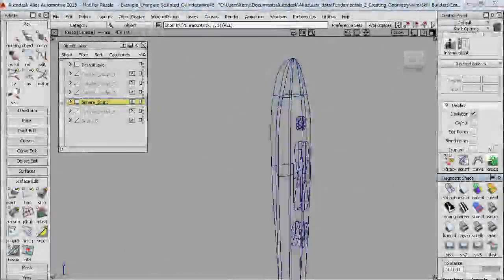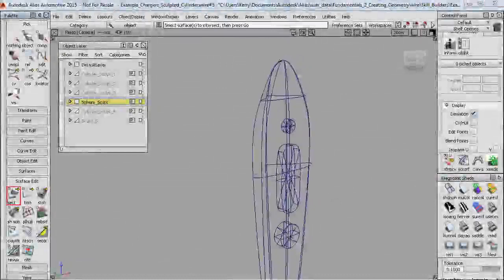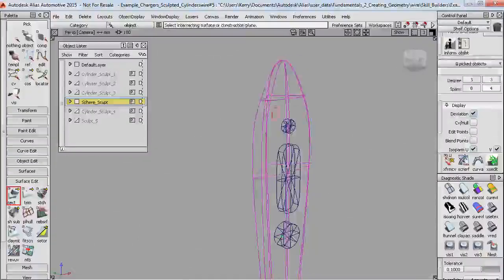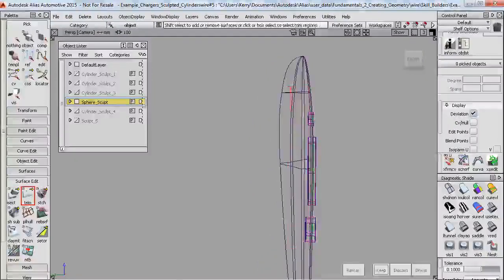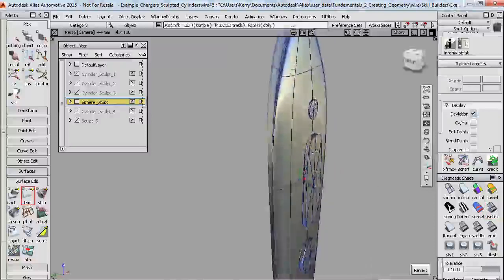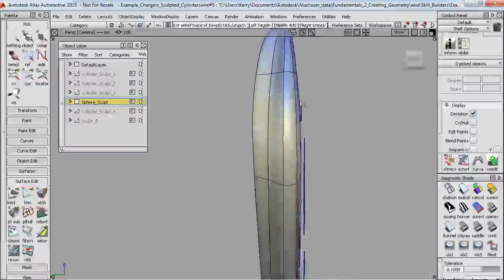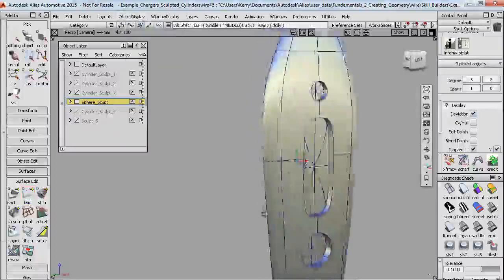You may also want to take a look at some of the shapes you did in the skill builders in section 2, where we just placed primitives together. But now you can intersect them. And then with trimming, you can trim back the main surface, and if you're careful, I should be able to trim all of these cylinders in one go. And instead of having them sticking out of the design, I can have them as indents. But because they were grouped primitives, I've got these end caps that I need to pick individually, and I'll just make them invisible.